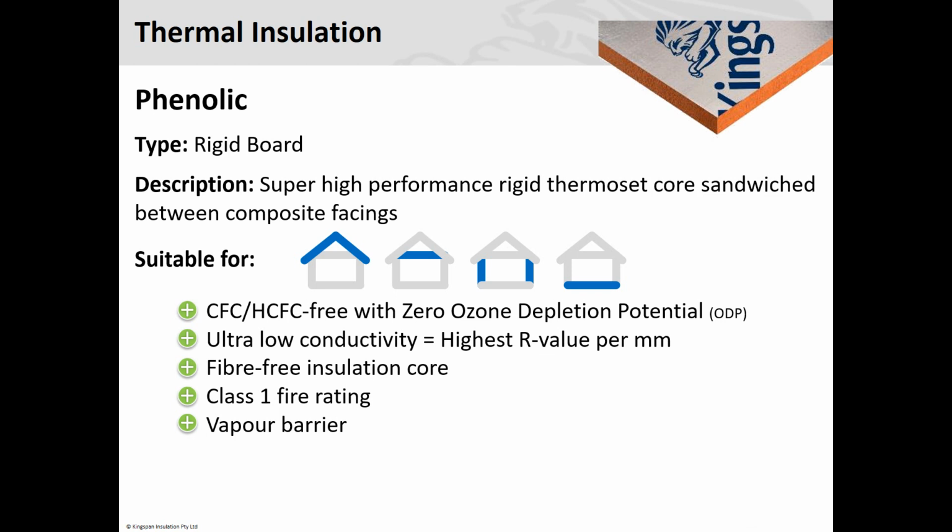So pretty much what would happen is, once you've dug out all the footings and the trenches and the Fortecon has gone down, you then put your Kooltherm, called K3, down. Then your reinforcement mesh would go on top, so the chairs to support the mesh would sit on top of the Kooltherm K3. Then your heating would be wired to the mesh, so it's all tied in, and then the concrete's poured.